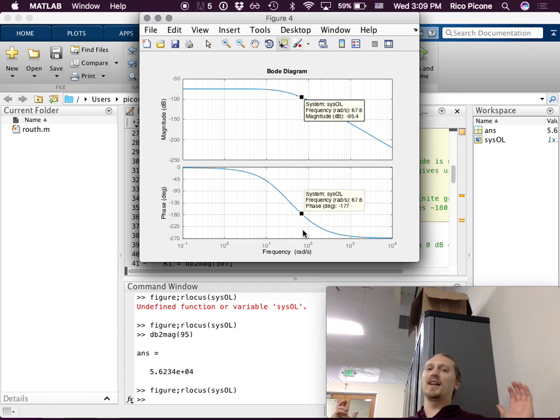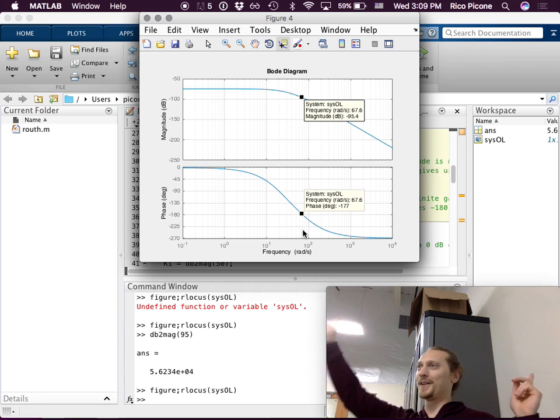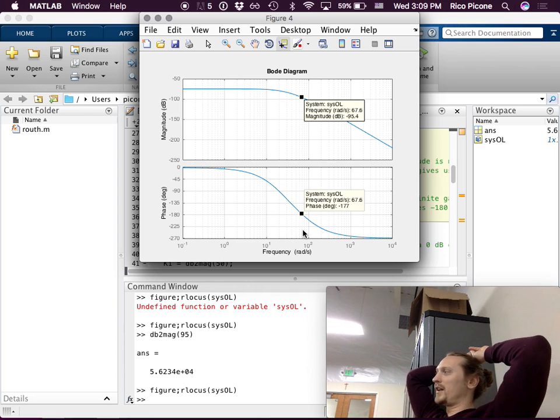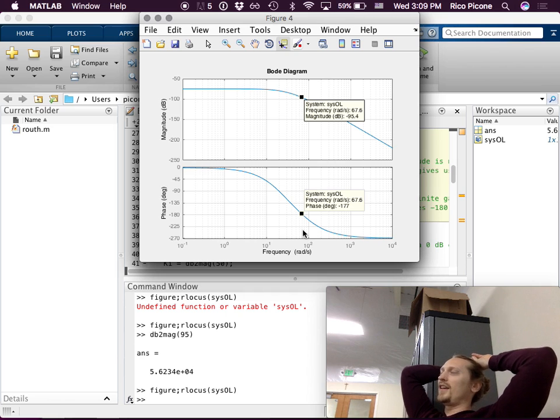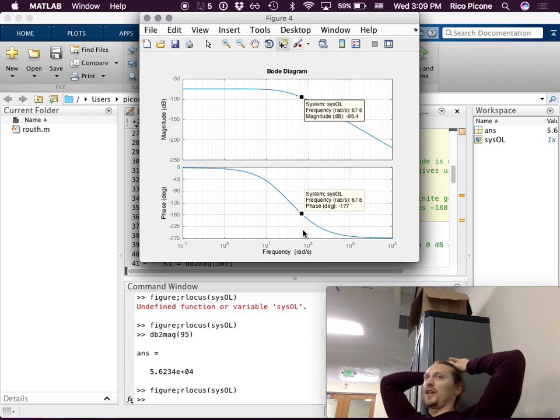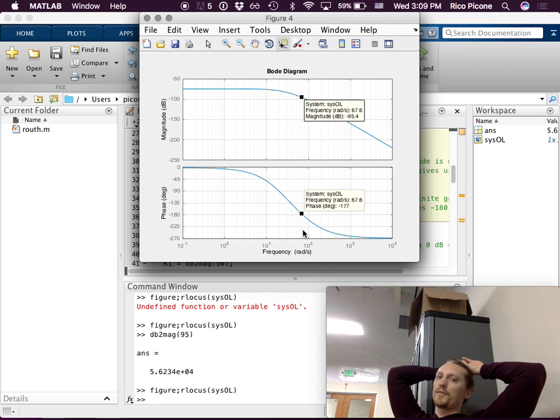So with the Bode plot, it doesn't leap out at you that there's a certain gain at which this system goes unstable. It does when you look at the root locus plot, right? It's like, oh, clearly this goes unstable. The information is in there, it's just more hidden. Same with the Nyquist. It's more obvious in the Nyquist than it is in the Bode that it goes unstable, because the encirclements are pretty easy to see. But the Bode is easier to work with for designing how much to increase the gain and all that. So that's why we work with the Bode plot.